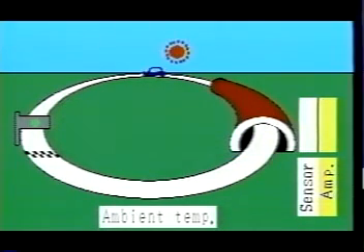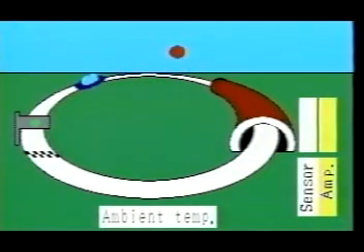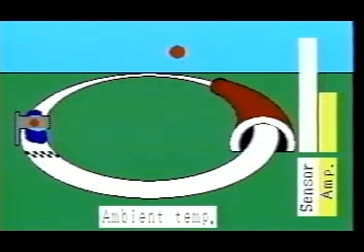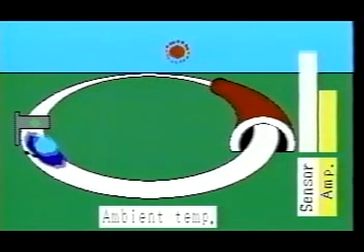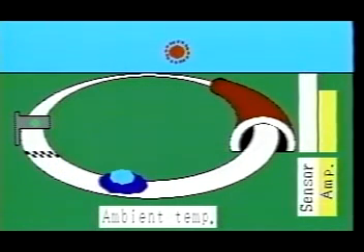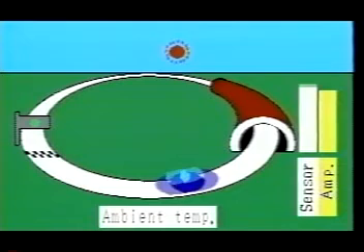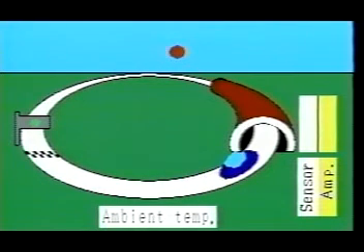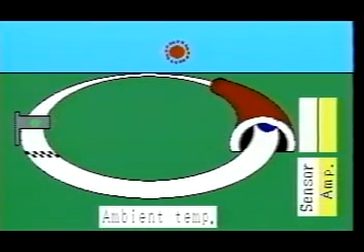When the ambient temperature rises suddenly, the automatic amplifier will only recognize the ambient temperature increasing at 0.36 degrees Fahrenheit per 60 seconds. Therefore, it takes 5 minutes for the automatic amplifier to rise 1.8 degrees Fahrenheit, which prevents the auto air conditioner from making sudden changes of outlet air temperature, air volume, and air outlet position.